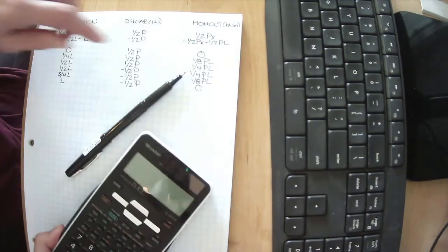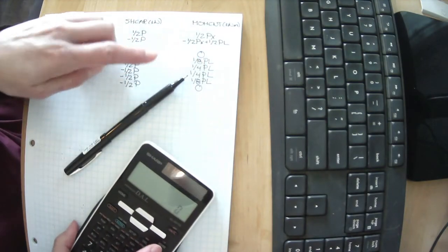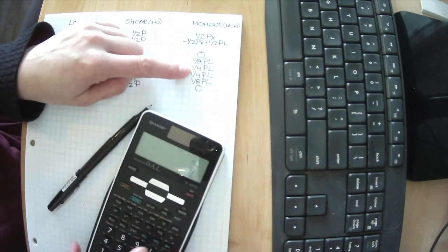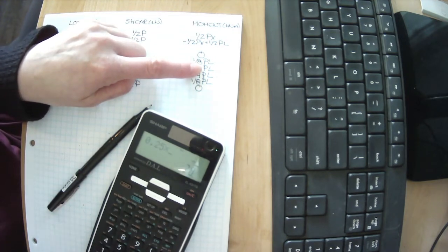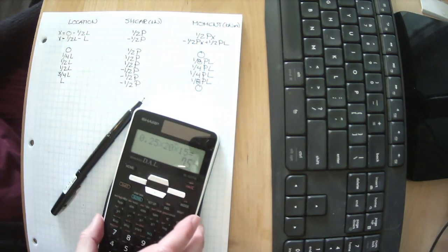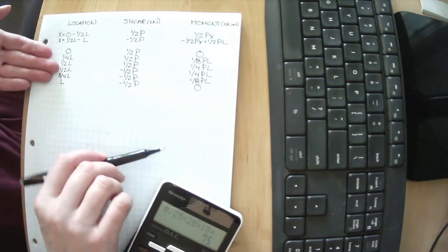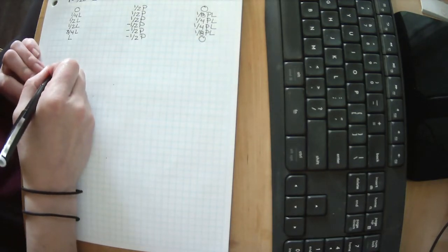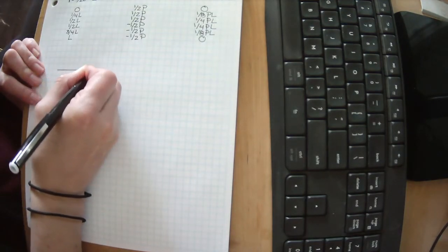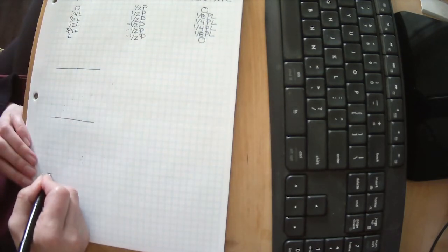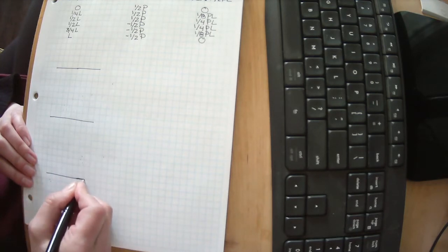What if we had a 20 kilonewton point load on a 15 meter beam? At the mid-span, we had 75 kilonewton meters is what we calculated. So 0.25 times our 20 kilonewton point load times our 15 meter beam. Look at that, 75 kilonewton meters. So we've actually done this with actual numbers. This is a handy little shorthand. Let's redraw that free body diagram, and our shear force diagram, and our bending moment diagram.